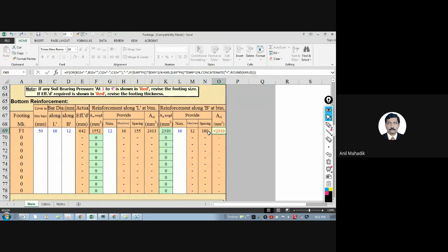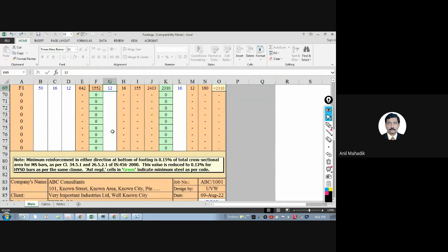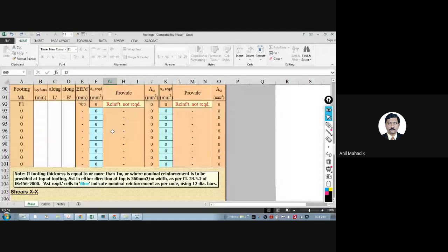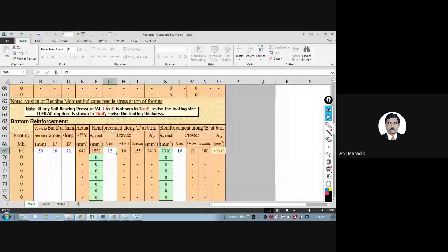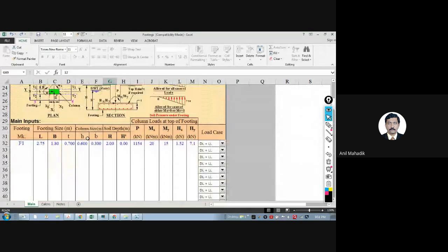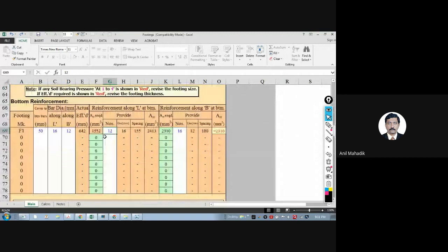So whenever you change anything, again go to the other parameters and check. Once you change the depth, you need to change the steel again. Here it was saying wrong design, because minimum AST is not satisfied because depth is more.